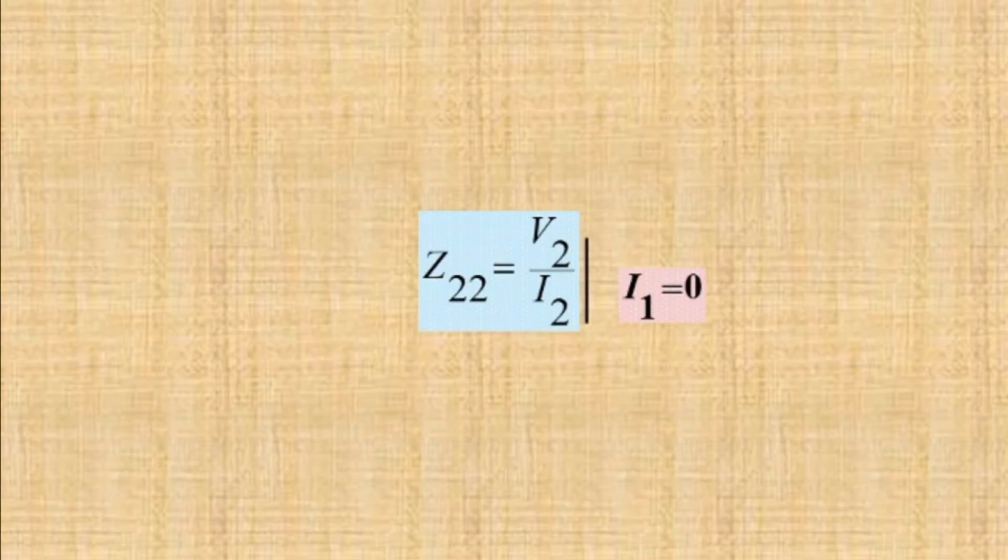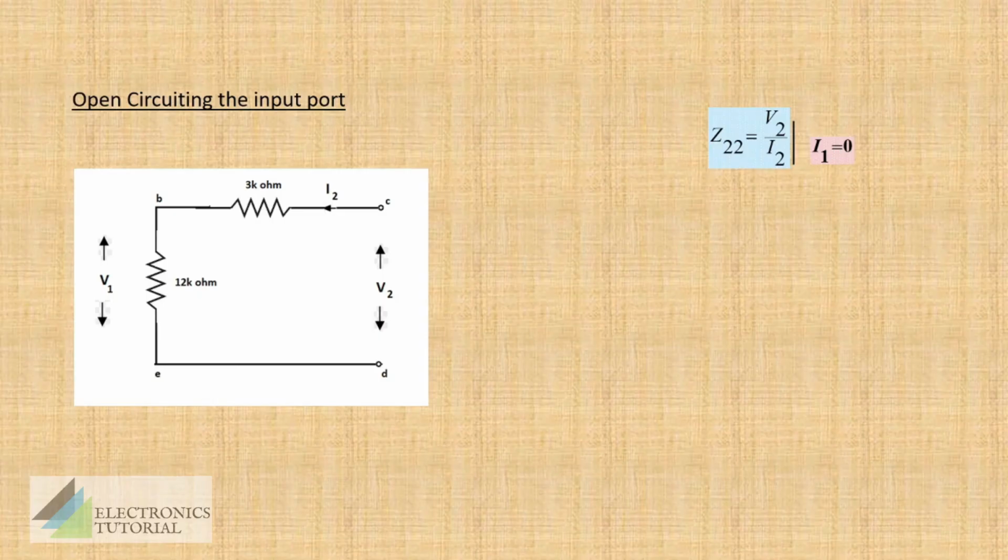What we have to do is, we need to make both the numerator and the denominator of similar terms. For example, here we have V2 in the numerator. Somehow, if we are able to express V2 in terms of I2, then the numerator and the denominator will contain similar terms. Then it will be easy for us to simplify. The choice is yours whether to change the denominator or the numerator. I have chosen to change V2. V2 is seen here in this position. Are we able to write V2 in terms of I2?